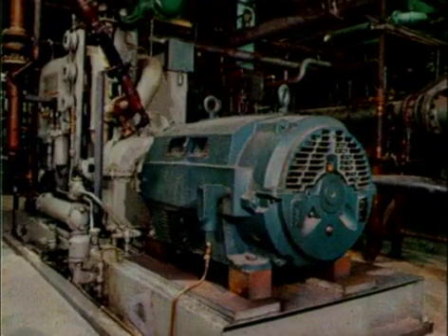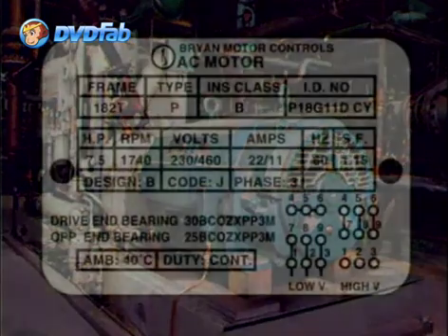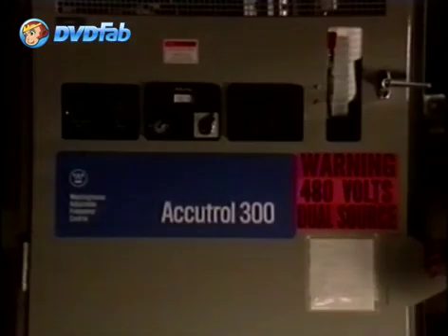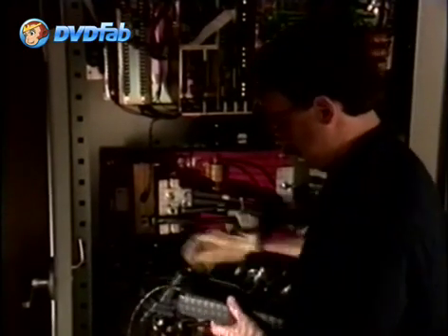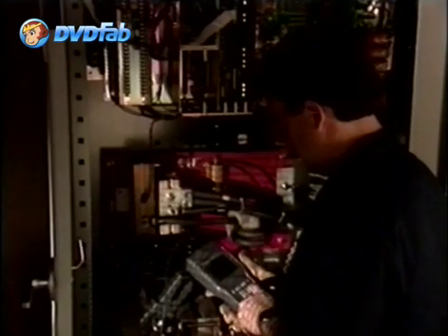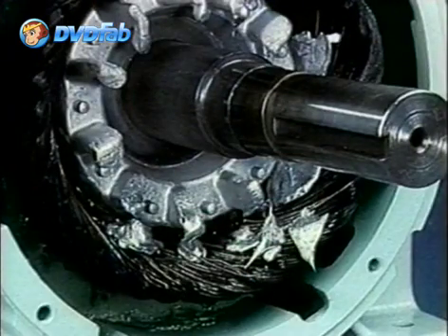So when we replace or install a new motor, make sure you check and document its incoming voltage against that of the nameplate. We already know the problems an imbalanced line can cause, and this is especially true with motors. In fact, this can be the silent killer of motors because it is not easily recognized until some damage has already taken place.